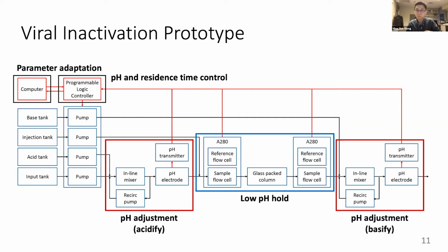And by residence time distribution, do you mean the variation in residence times that happens during the operation of the system, kind of long term? Yes, because like I explained before, we want this low pH solution to remain for a certain amount of time, not too long, not too short. So the residence time distribution throughout the column in the low pH state is what we are interested in.